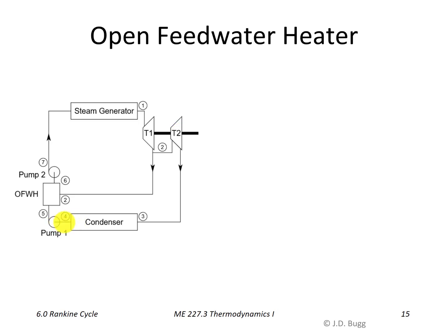So we have our feed water coming out of the pump, entering the feed water heater. So this is a relatively large flow rate of relatively cool water. Then we take a relatively small flow rate of extracted steam, so this will be at high pressure and temperature, and we mix these together. So these just enter this open feed water heater and mix together. That's why it's called an open feed water heater, because the two inlet streams are allowed to mix. So they mix together and go out this exit here. So an open feed water heater has two inlets and one exit. And like I say, it could be as simple as just a T in the line. We have this pipe flowing along and then this is T'd into it. Schematically, I'll just be showing it as a box like all of our heat exchangers are.